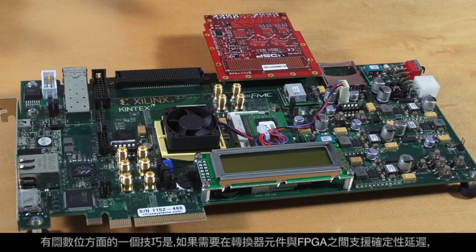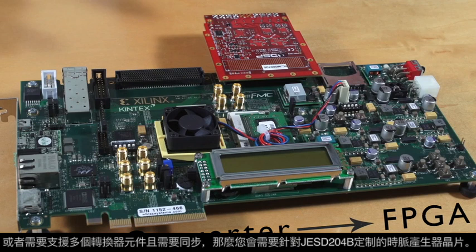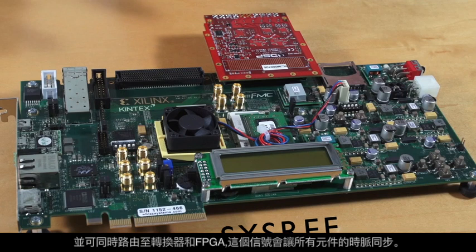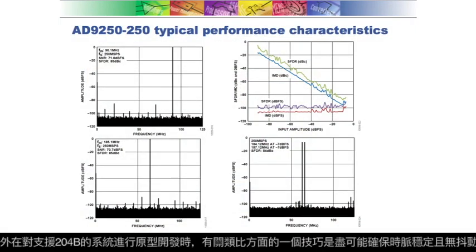One tip on the digital side of things is that if you need deterministic latency between the converter device and the FPGA, or if you're using multiple converter devices and need coherency, then you will want a clock generator chip tailored for JESD204B. In addition to generating the necessary high-speed clocks for the converter and FPGA, such chips also make a sysref signal that gets routed to both the converter and FPGA. This signal keeps everybody's clocks synchronized. It works just like in the old movies. Gentlemen, synchronize your watches.